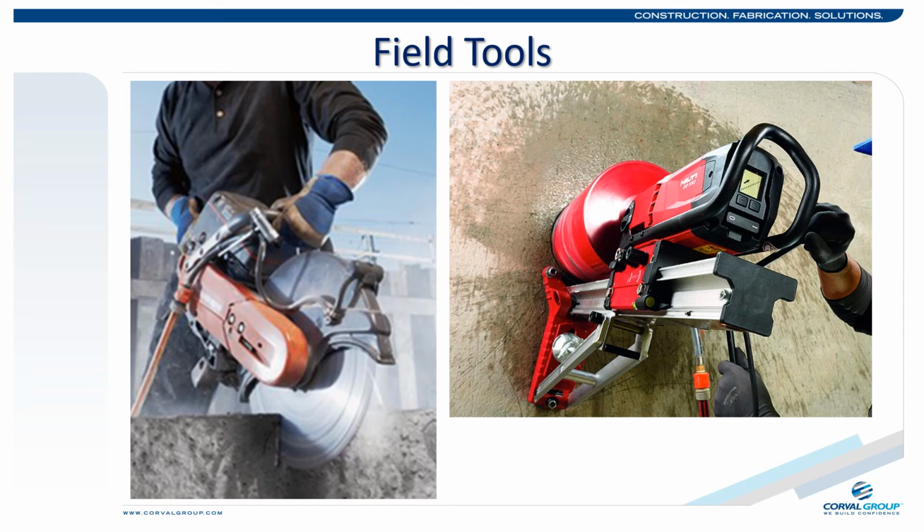They have somewhat removed the dust issue before it was an issue. However, the same tools cannot be used dry under any circumstance, and there will always be a slurry left over. As this slurry dries, it can form a secondary exposure to anyone cleaning it up. Dry sweeping is forbidden by the OSHA standard and replaced with HEPA vacuuming. We will cover this further in a few slides.